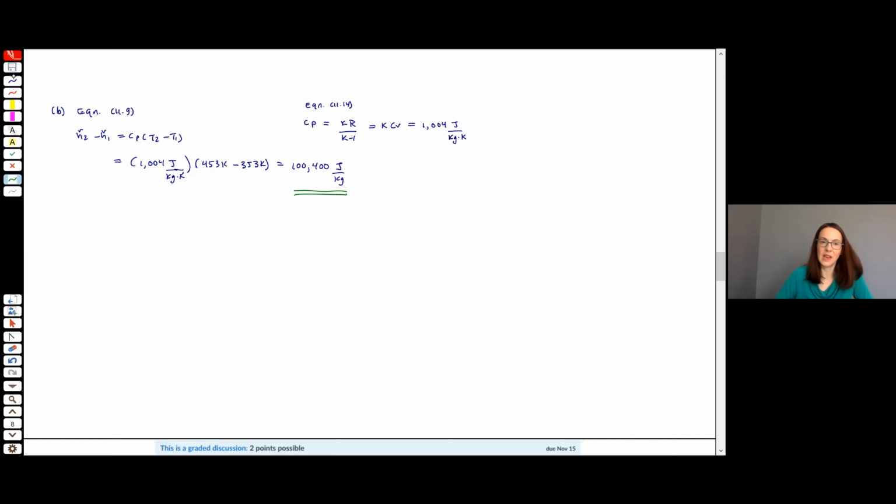So we see that the enthalpy is also increased from section 1 to section 2 as the fluid's been heated. It looks like it's increased a little bit more. Notice the units, right? It's joules per kilogram. So this is per unit mass, right? This is an intensive property. And if you wanted to get the quantity for the entire volume, you'd have to multiply by the mass.